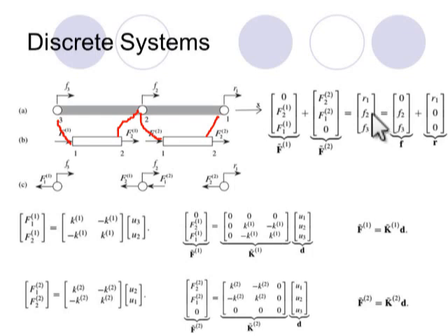There's then another thing that we do. Now remember that we know F2 and F3. These are external forces and are given to us. But we don't know the reaction force. As well, we don't know the nodal values of the internal forces. As a result, we divide this force vector into two vectors: the ones with the known values and the ones with the unknown values.